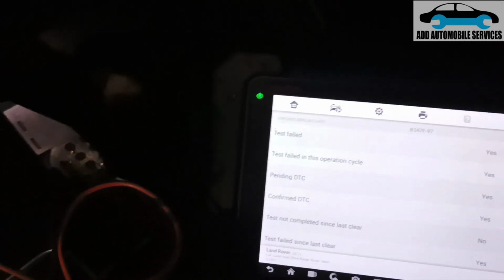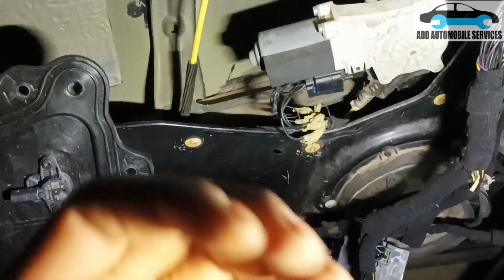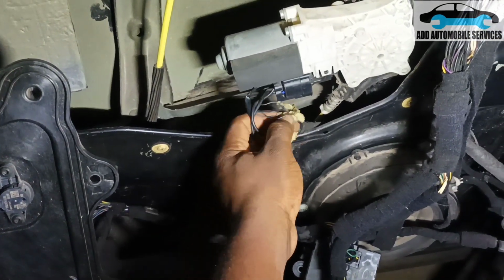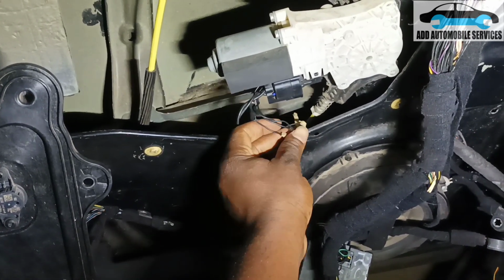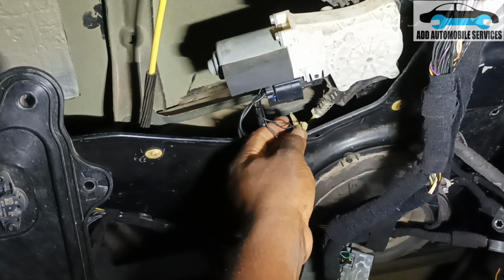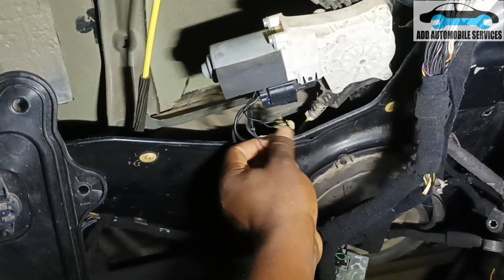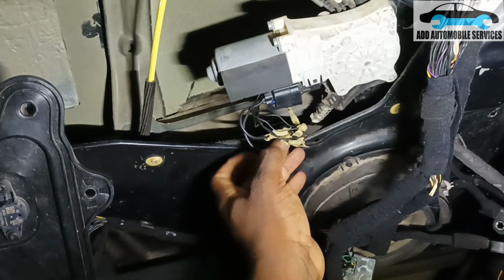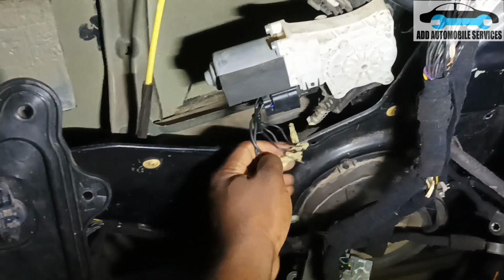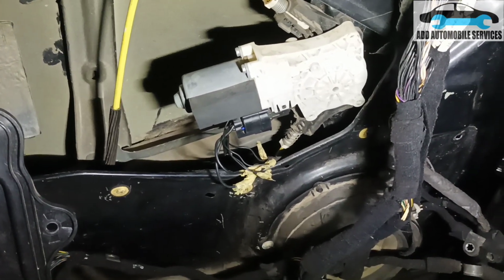This window uses a Hall effect sensor to know the position, and when I opened it, this is what I saw. So it could be that maybe there is an error here. They've messed up the wire. So what I'll do is check this connection, because I know it's supposed to be one ground, one 5-volt reference, and the other two supposed to be the 2 Hall effect sensors. So I'll check and retape all this wiring again, redo them nicely. I'll check the wiring diagram and check them.